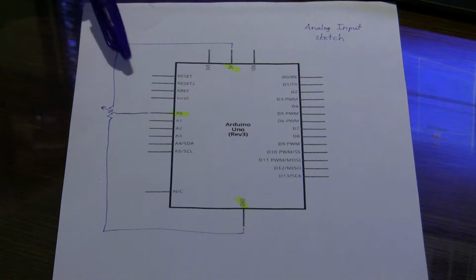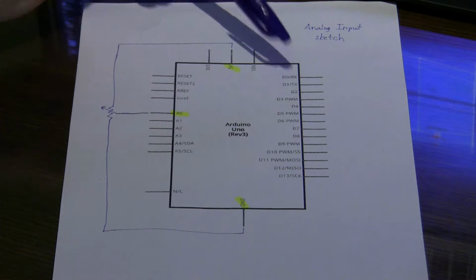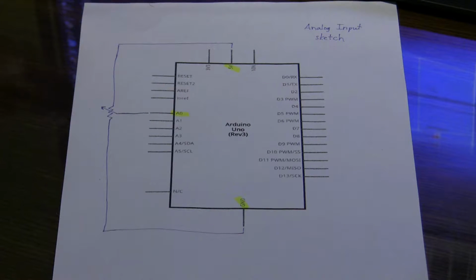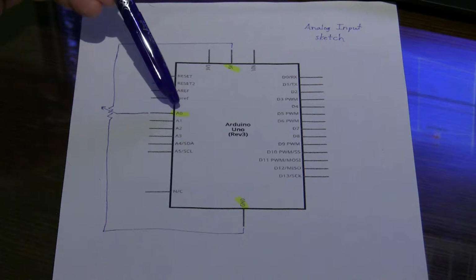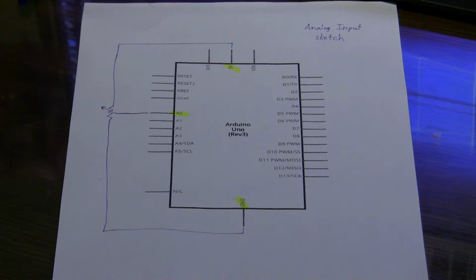So if you remember in the last sketch when we did the button input, it was wired to pin number 2, which is a digital pin. So it could only read 2 values: on, off, high, low, however you want to put it. Apparently the analog input pins are able to read a range of input values. So that's going to come in handy when we turn the knob on the variable resistor, and it should be able to give us a reading of the relative position between the lowest and highest value of our resistor. So we should see how that works when we get to the code.